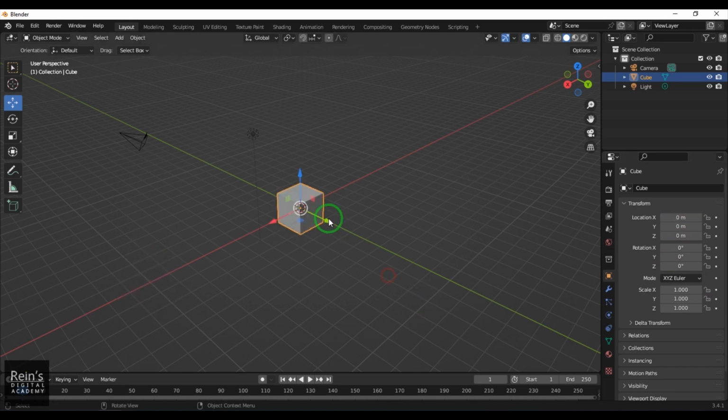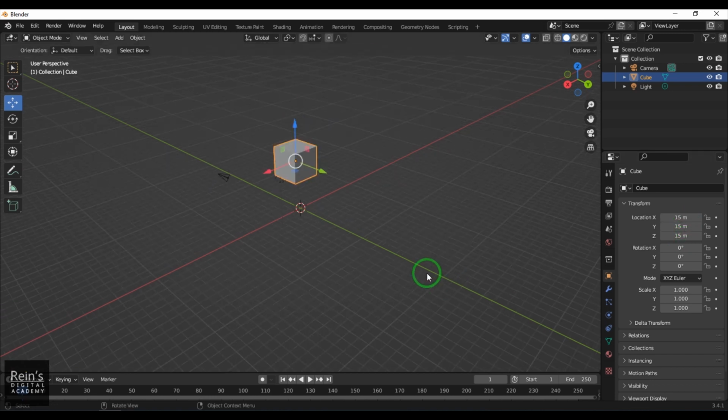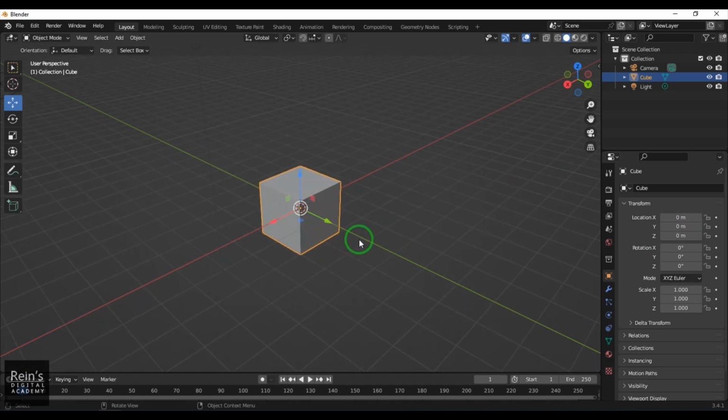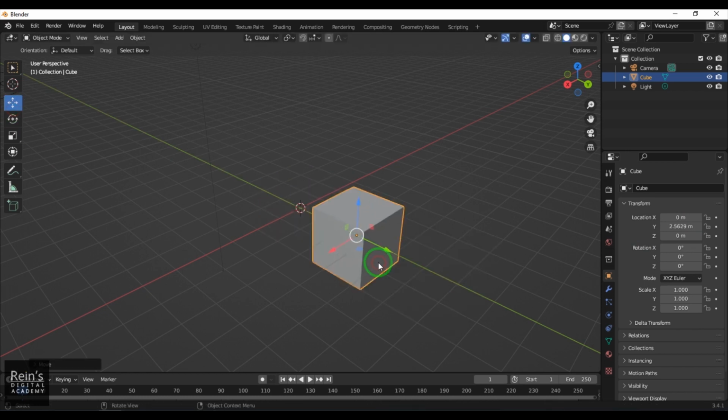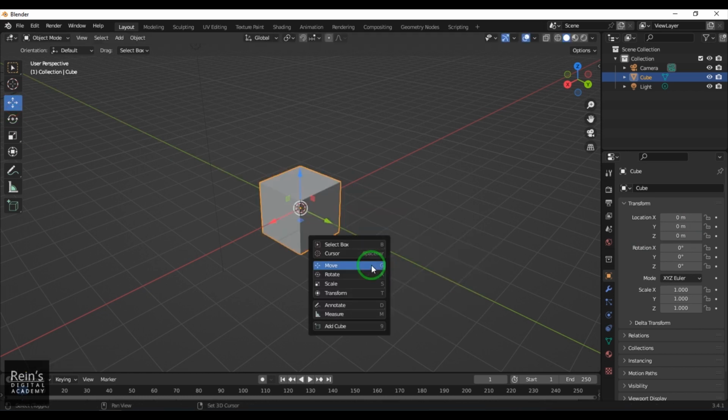And if I have different numbers here, I need to just select that, put the cursor there and hit backspace. All the values become reset, or it will go back to 0. So the move tool is generally used either from this tool where you get the manipulator, or I can press shift space, or you can choose the tool from here. I can also use G and then manipulate. So these are all different options for how you can use the move tool.